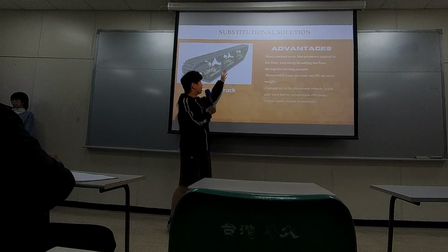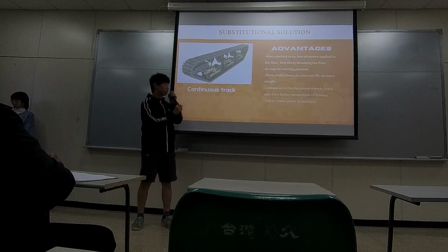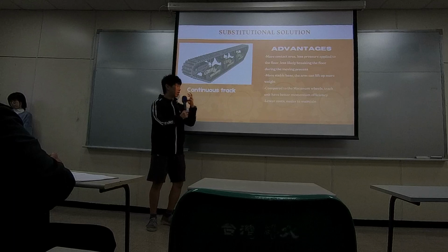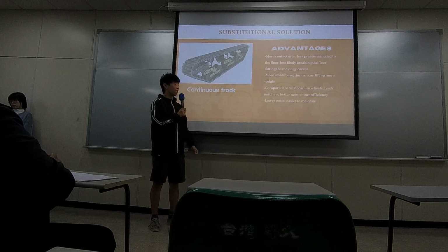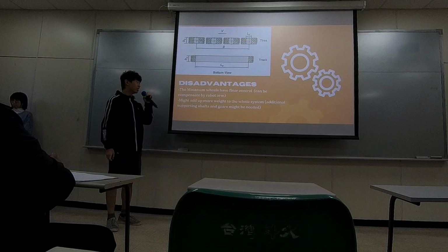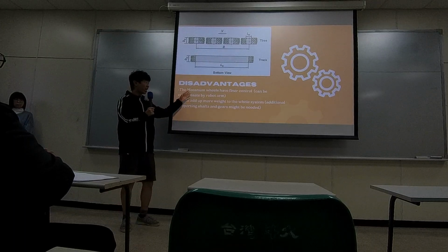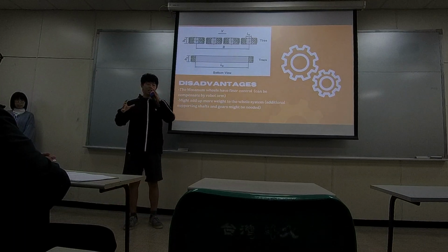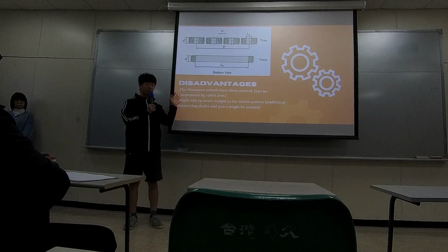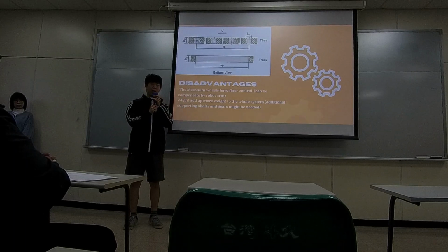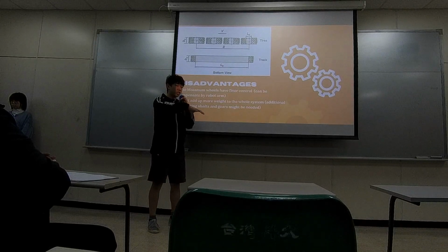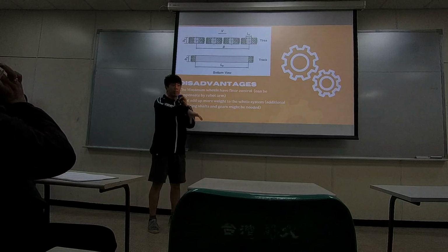Compared to that, the track unit can have a very significant improvement. The track unit is also very cheap and very easy to maintain. The disadvantage we think of is that the wheel can have finer control, so the robot moves very precisely. But I think this can be compensated by the arm, because when moving the track unit, we can have an error of maybe 10 centimeters.